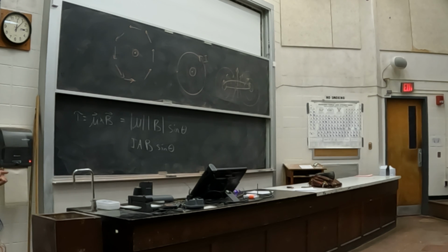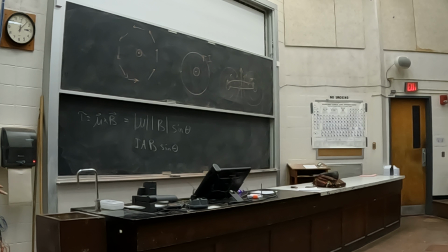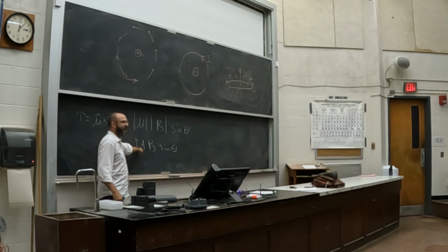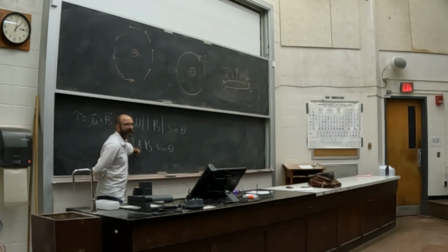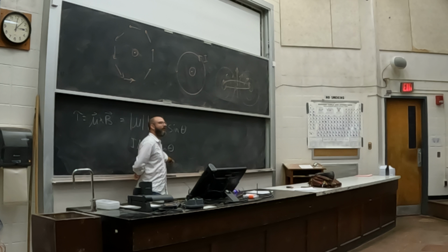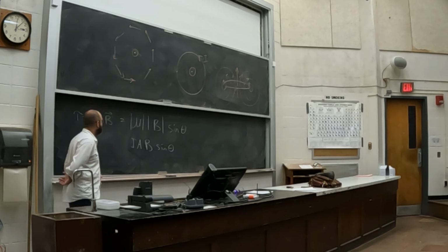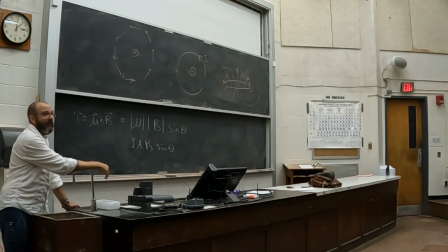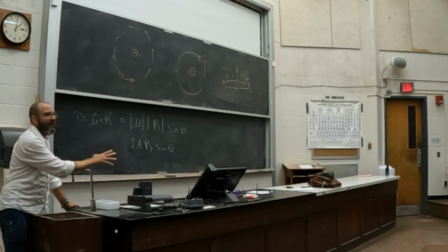This tells you that if you're going to produce a torque, there are several different ways to do it. You can change the current, which is what the solution was here in the DC motor in the commutator. You can change the area of the loop. That's a little difficult, but there's situations in which you can do it. Railguns. You can change the magnetic field. That's a possibility. Or you can change the angle between them. Any change in any of those is going to change your torque, right? So how you choose to formulate that is kind of up to you as an engineer and your design specification. But a change in any of those things will produce a changing torque. All right, questions about that?